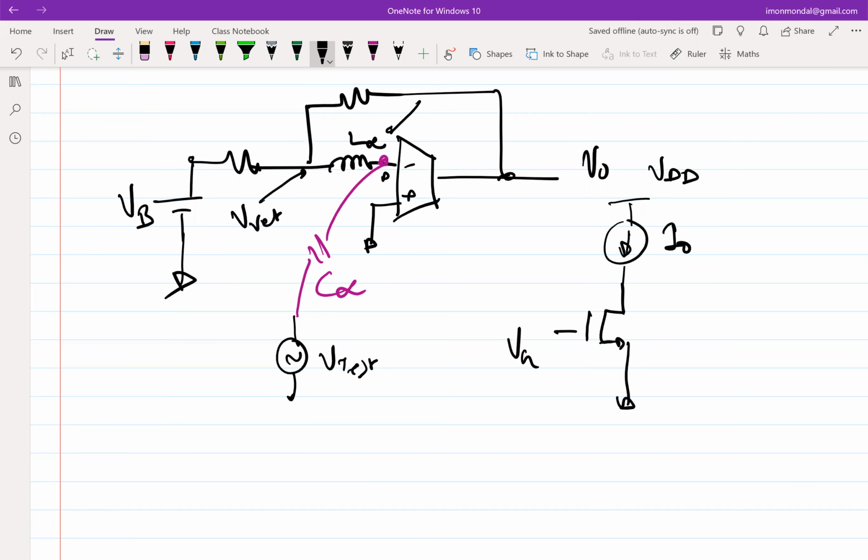Doesn't really matter. So what will essentially happen is that this voltage will keep on increasing because you are pumping current I0 into an open circuit. Now it depends on how good your I0 is. Whatever voltage it can sustain across it, it will sustain. After that, it will break down. There's nothing else. It's an open circuit.